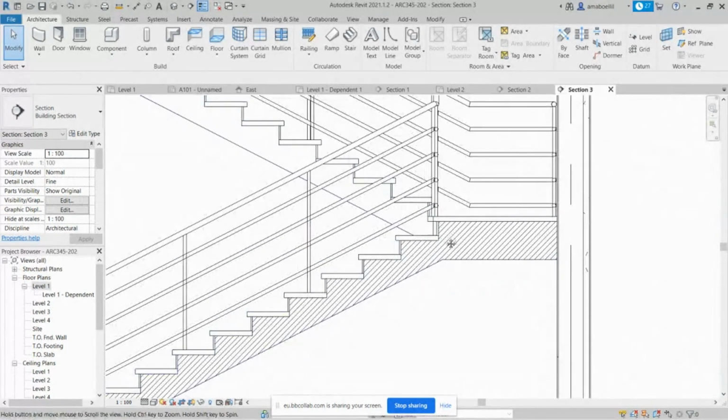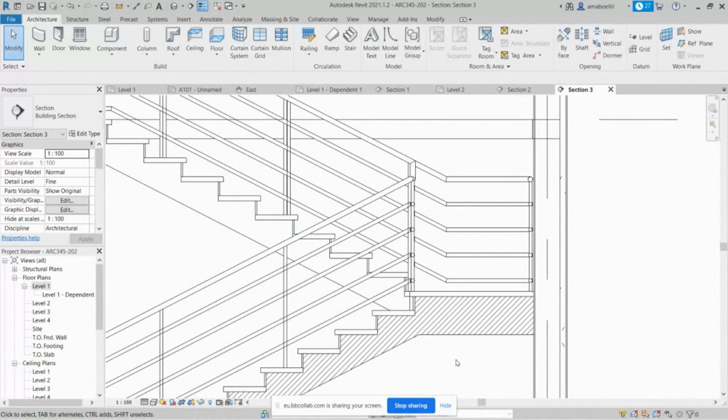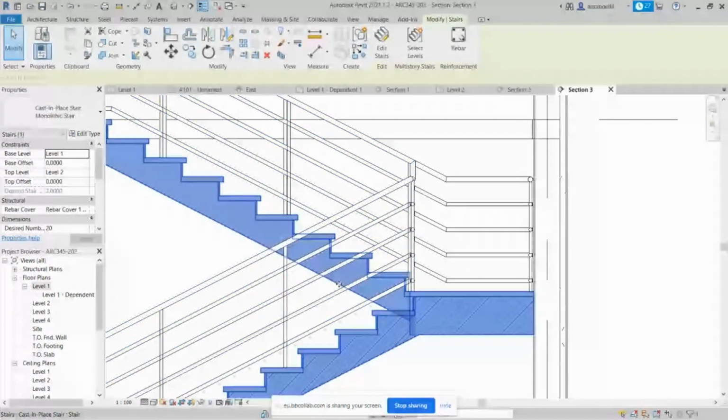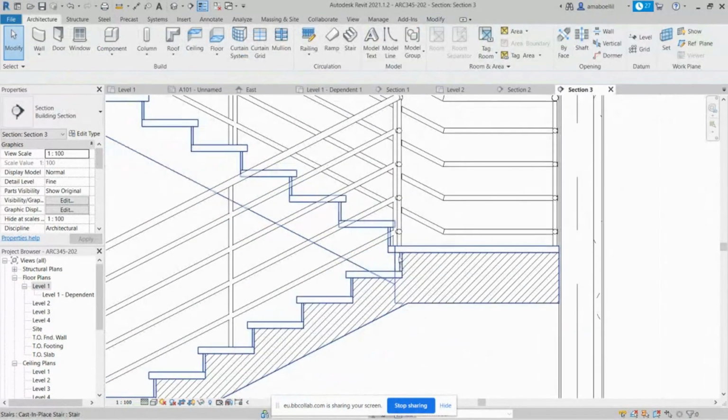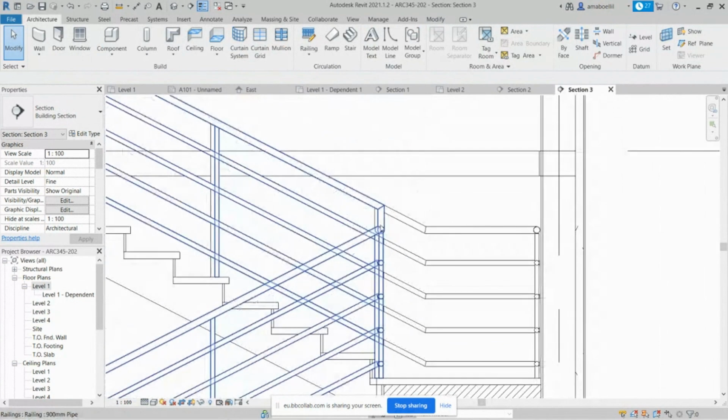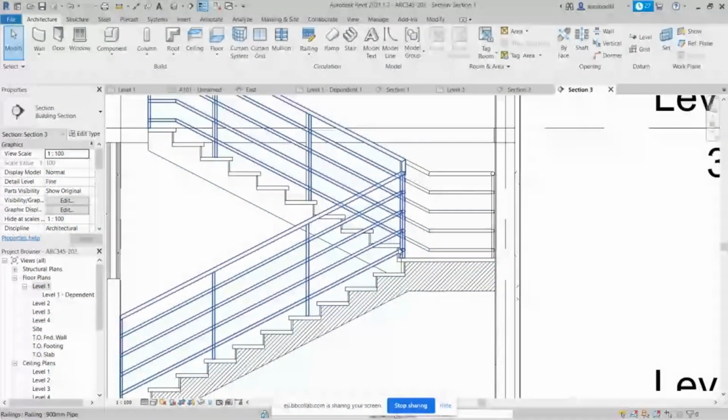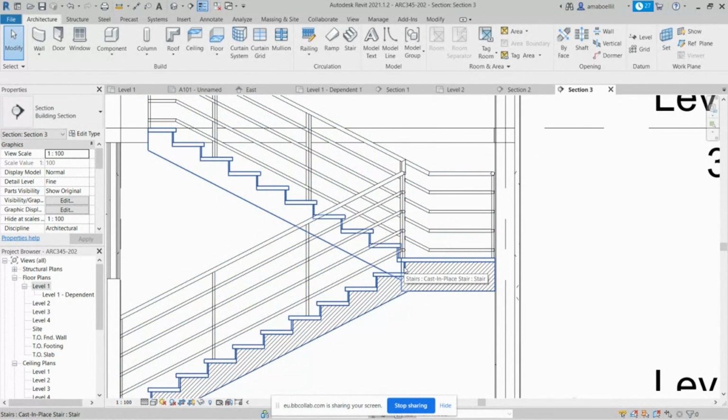One of the things also is that when they look at the drawing, they might say a professional architect or a professional detailer did this, because you would see that this line, the bottom here and the bottom there, meets at one point. You see that here it's not, because of the issue that I told you about, that the stairs are not the same. So the bottom here and the bottom there and the bottom here should meet at one point, and you extend the line for it, and then the guardrail or the handrail also meet at one point, and this goes down and this goes up. If you make this detail properly and make the stair here one before the other, the starting of that is before the end of this, or after it, it will fix itself.